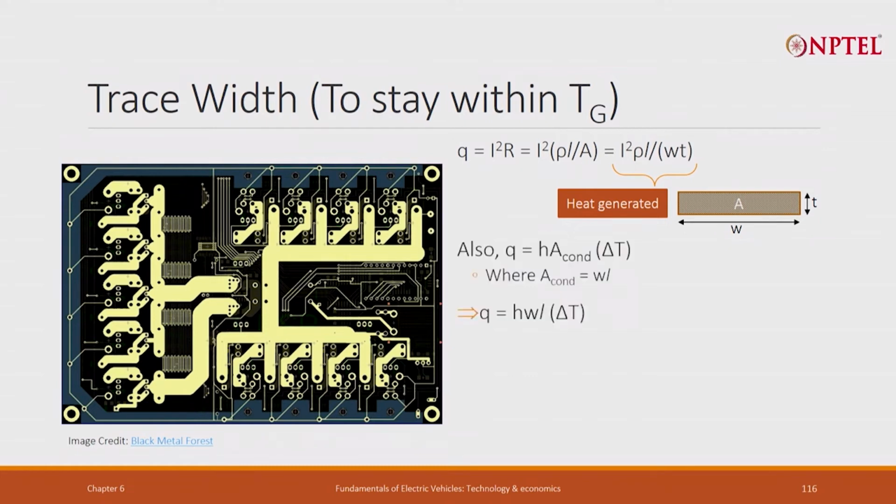Now, how much heat is being removed is what I want to know, and I told you in steady state, when the temperature is not rising, not falling, the heat added must be equal to the heat that is removed, and the heat removed is H, which is just a constant. We have already seen what H is, heat transfer coefficient, or the interface conduction coefficient.